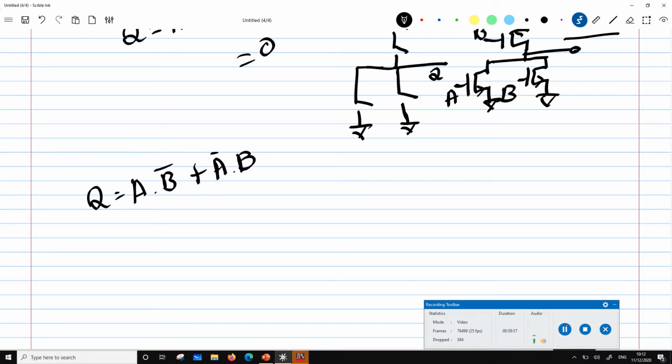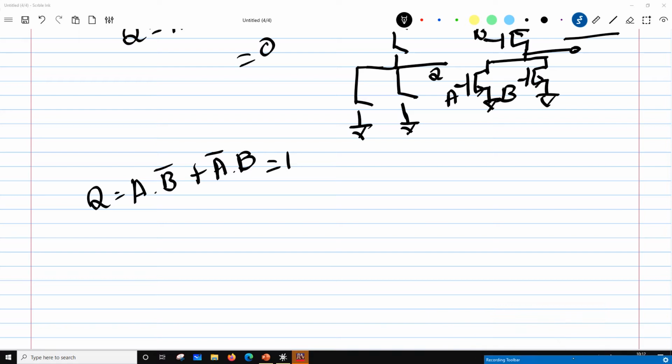So now how would you design a XOR gate? Let's go this way. Let's equate this to 1. So I'm constructing a pull-up circuit, right? So when I equate this to 1, so what I need, both of these expressions, they are both, right? Not both of them, sorry. For pull-up, either of them has to be 1. So if it is either case, then one circuit is in parallel with the other.